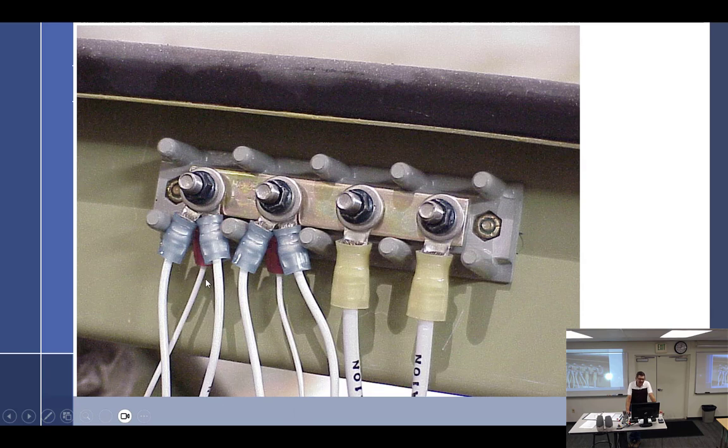The next thing I'm going to write here is, and this is a Q&A question, it's just a known fact in aviation. These are terminal ends or lugs here. The most you can stack onto any one of these is 4. These are a phenolic block, like a plastic, and a terminal block is what it's called. This could be like a bus bar. This could be the power in right here. This could be battery, this could be generator, and then these are the loads. It's very small for that, but it's an example.